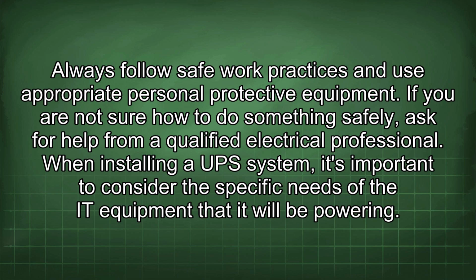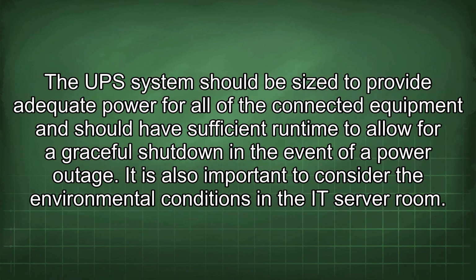When installing a UPS system, it's important to consider the specific needs of the IT equipment that it will be powering. The UPS system should be sized to provide adequate power for all of the connected equipment and should have sufficient runtime to allow for a graceful shutdown in the event of a power outage.